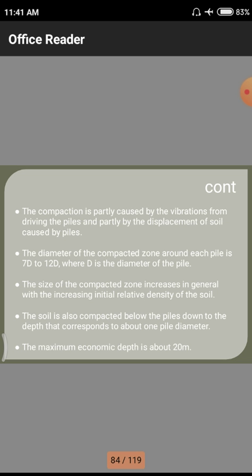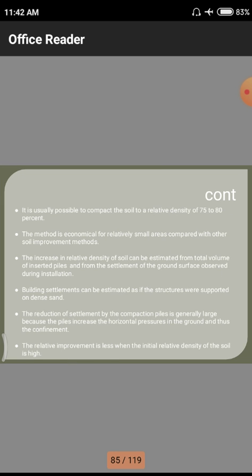That means to drive through those hard rock strata we need a huge amount of equipment and money power. We have to use too much power in terms of electricity or any other fuel, so that the total cost will rise after 20 meters. Up to 20 meters we are having an economical value. After 20 meters we need a huge amount of economics for the particular soil strata, so we need to remember all those things while we are driving a particular pile on the soils.